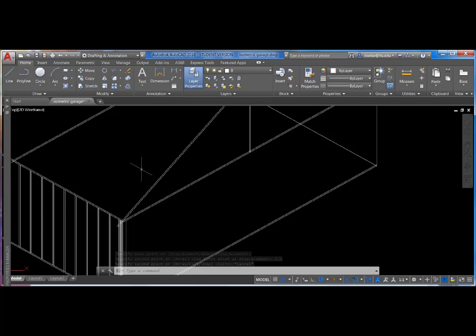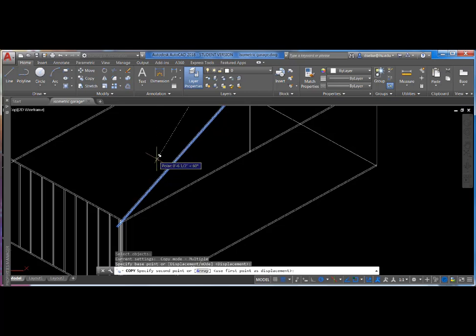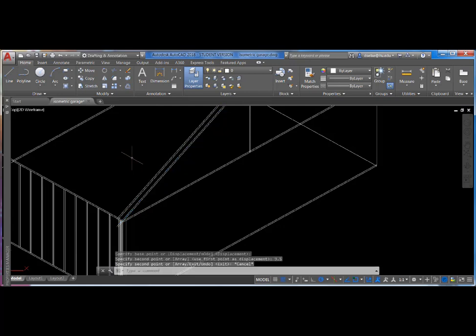So now my rafter is actually 10 inches. It's a 2 by 10, so it's 9.5 inches tall. I'm going to go ahead and copy that. Copy it up to make the rafter. So this time I set my polar coordinates straight up at 90, type in 9.5, and this shows me the top of my rafter.